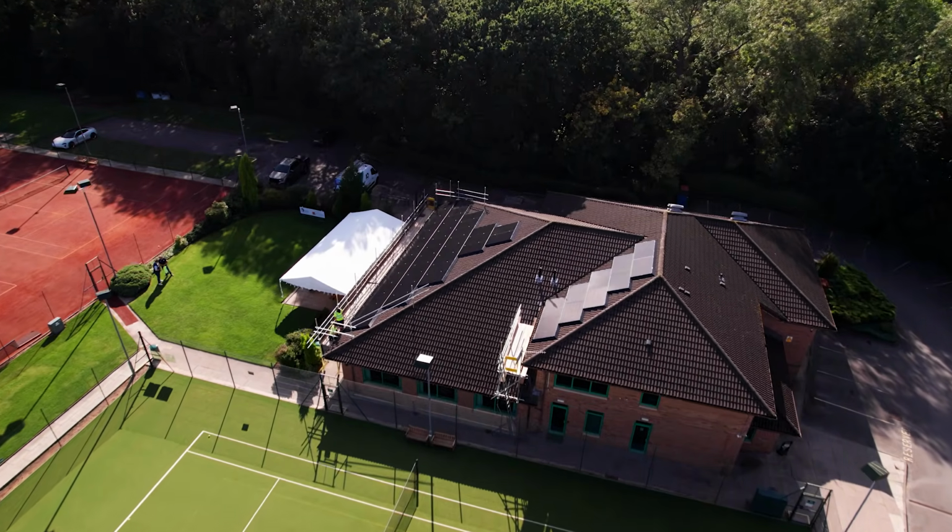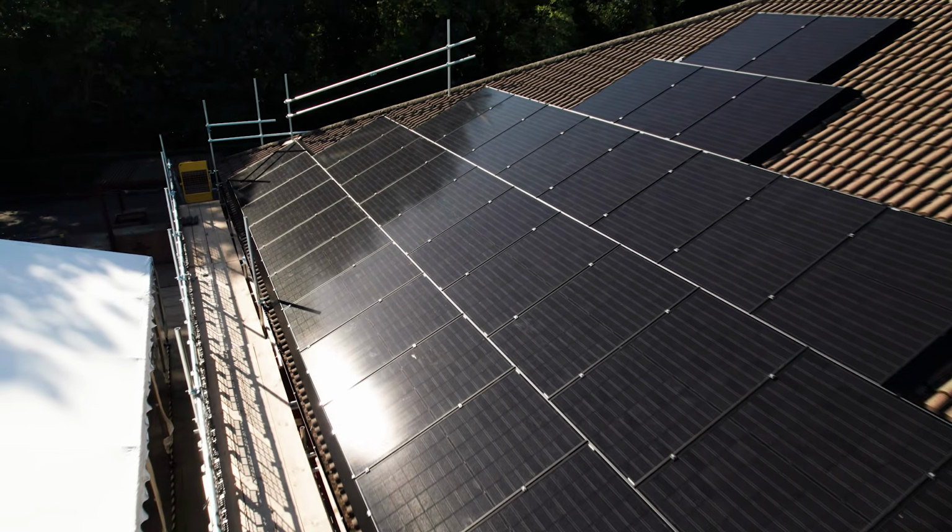This clicks onto the back of a solar panel and this regulates what this solar panel is doing. So as this solar panel tracks into this shade, that panel's now sat in the shade. That panel can essentially turn itself off, disconnect itself from the circuit using electronics. As the chimney stack moves on to the next solar panel, that solar panel can fire itself back up again, and this solar panel will turn itself on. So if you've got really heavy tree coverage, if for example in the winter it's completely covered, then optimizers may well be a great key component.